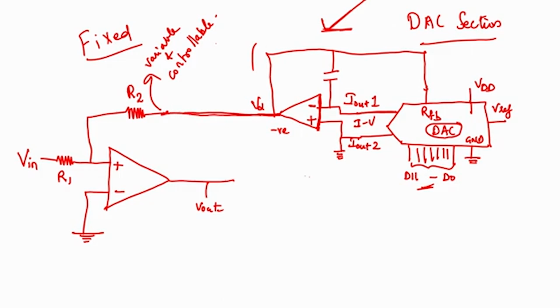So this voltage that is coming from here, this part, gets configured by this bit sequence and it gets added on to the feedback path. Now still the feedback part is not completed, correct. The Vout is still dangling here. The Vout should finally connect here. Ideally it was connecting here, but then we have added a changing negative voltage, a controllable voltage component there.